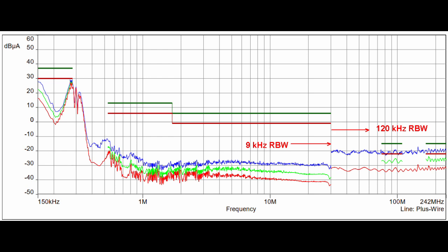So we have to measure peak and we have to measure average, and then from that we also measure quasi-peak. Quasi-peak is nothing but a level near the peak level of the noise, but with very high repeatability, and that repeatability of the noise is very dangerous. In the EMI receiver, we can not only detect the noise, at the same time we measure the repeatability, the amplitude, the level, all the things.